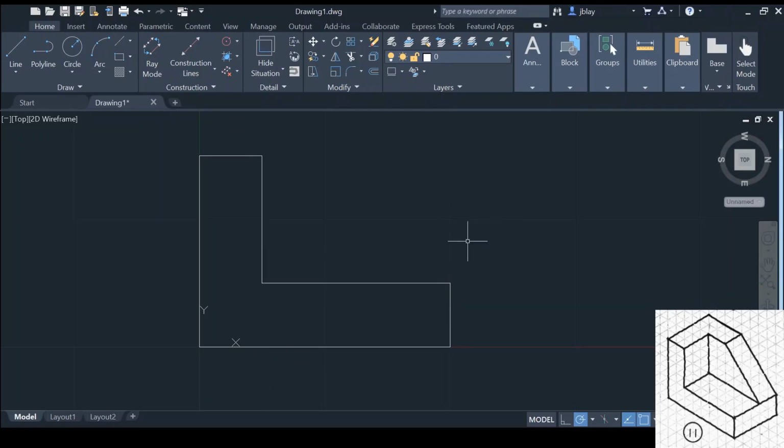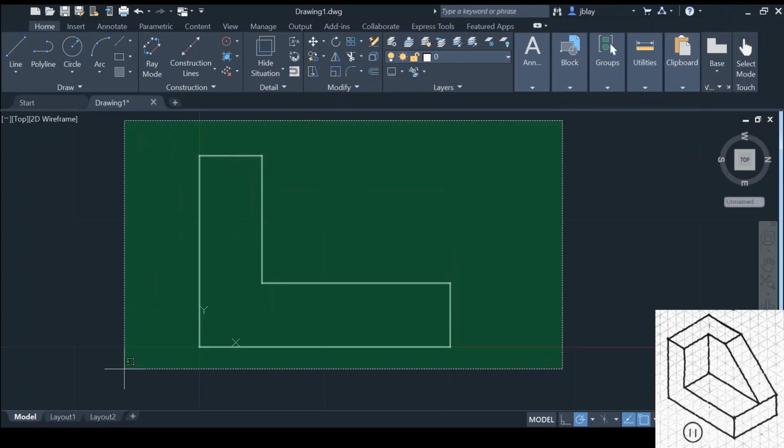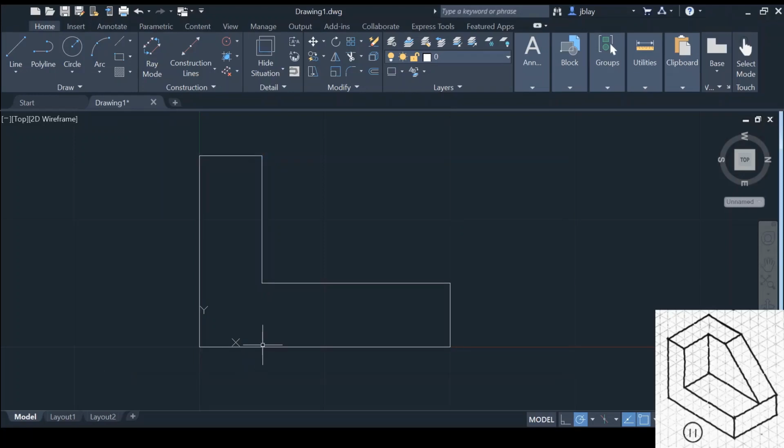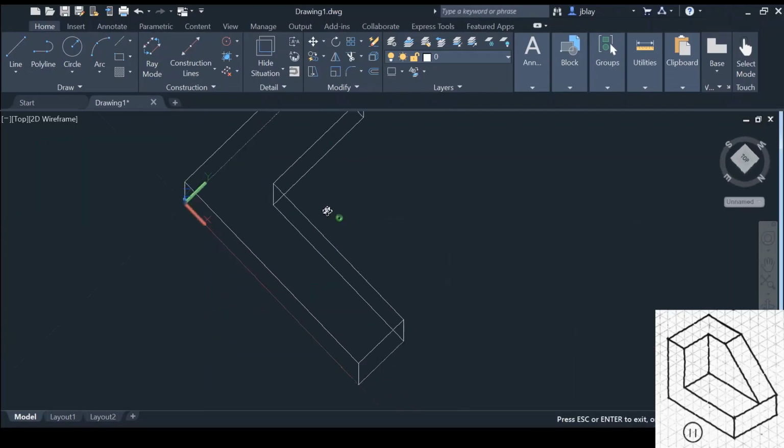Okay. Now this should all be one object because I used polyline. Oh, looks like it created 3 objects. I guess because I escaped polyline so many times as I was drawing the shape, I didn't just do it as one continuous object. So that's why it's separate. But that's okay. Whenever in doubt, just use the join command and combine them all. So I typed in join, hit enter, selected everything, hit enter, and now we have one object that we can indeed extrude. So we extrude by the depth, which is 1.25 inches. Then we have our shape.